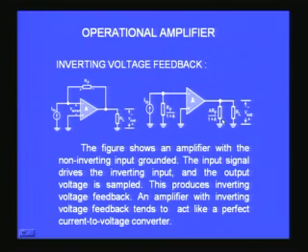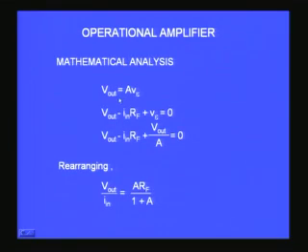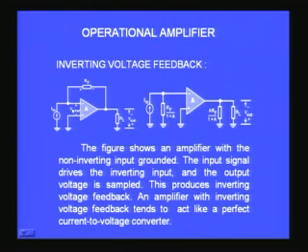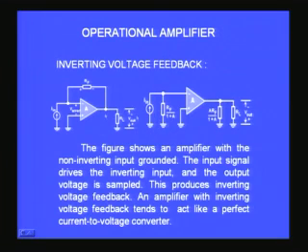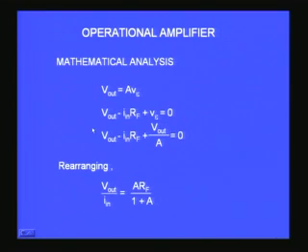So this way also we can discuss the circuit, and the output is A times V epsilon, where V epsilon is the small error voltage between the plus and minus terminals, and V output minus I in Rf plus V epsilon is 0 by applying Kirchhoff's law for the circuit here. V output, this is the I in Rf, this is the I in V epsilon, you can say. So this V epsilon is nothing but V output by A, so I substitute in the next line V output by A, and I can rearrange in terms of V output. So V output by I in will be equal to A times Rf divided by 1 plus A, which when A is very large, is going to be almost Rf, or V output is equal to I in into Rf, which is what we know.